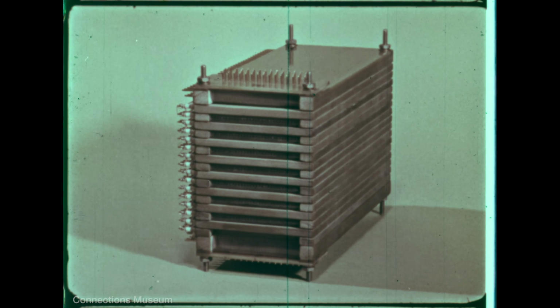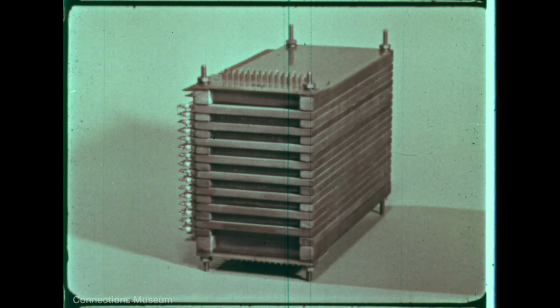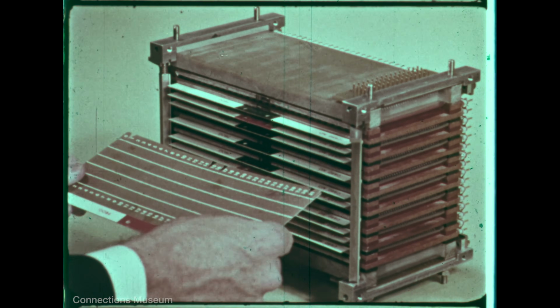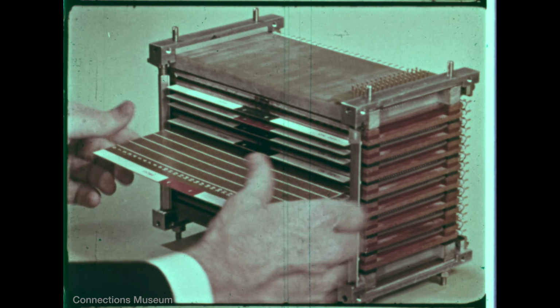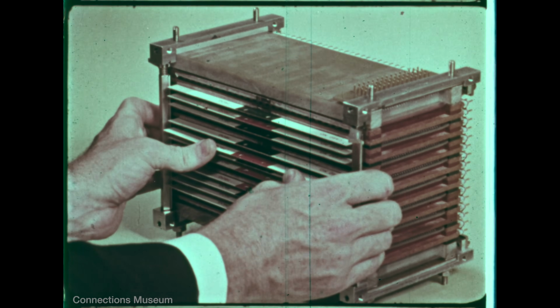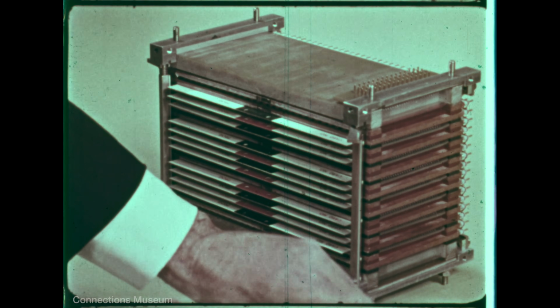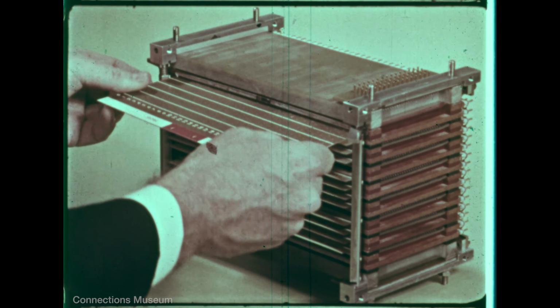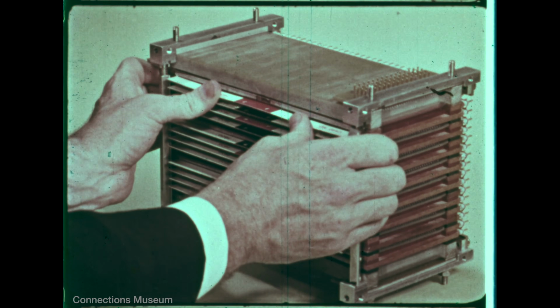The twister stores information temporarily. A permanent memory has been developed which uses the twister as a reading mechanism. On these cards, binary information is stored by the presence or absence of tiny permanent magnets. The cards are inserted in a twister module. When currents are applied, the presence of a magnet at an intersection inhibits the twister segment from switching. Where there are no inhibiting magnets, the twister segments do switch, thus reading out the permanent data stored on the card.